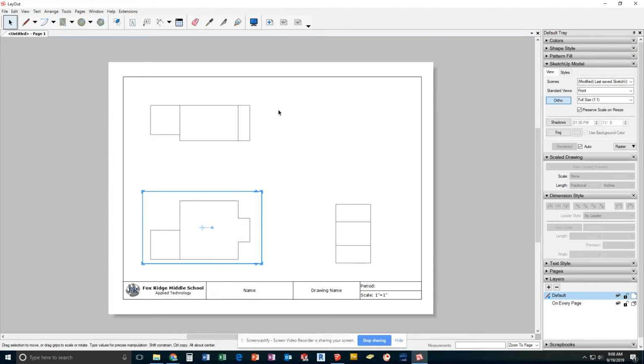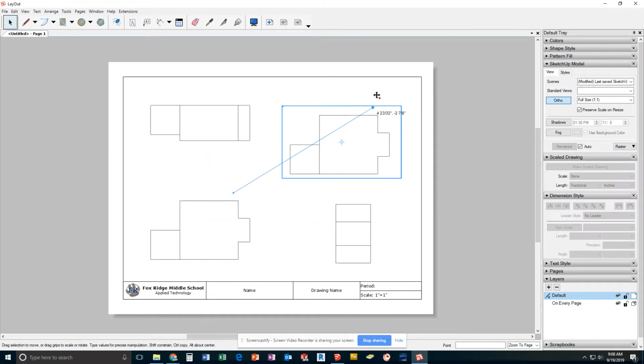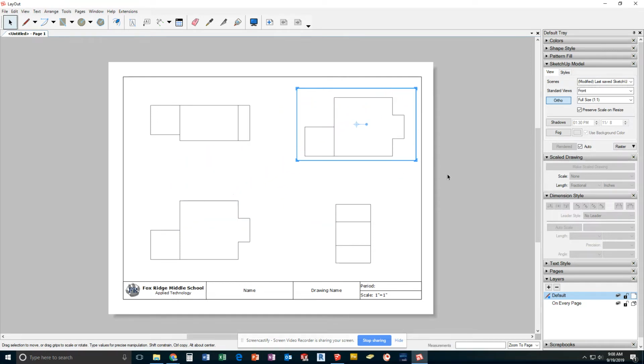Also, we're going to make what's called an isometric view. It's a 3D cool looking view that we're going to put up in the corner. So I'm going to hold Control. This is the only one where it doesn't matter what angle I put this at. So I'm going to kind of drop that up there, and I'm going to change a few settings here.